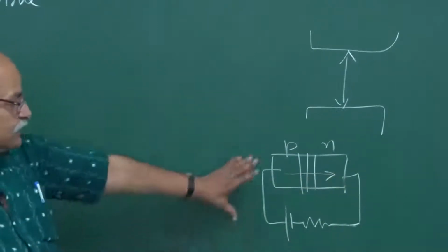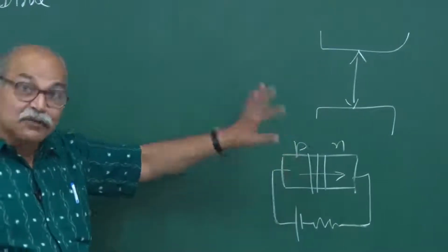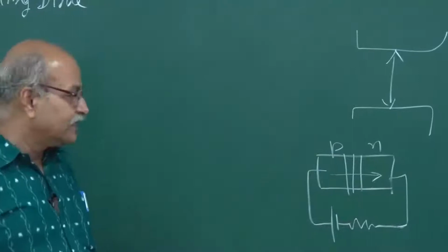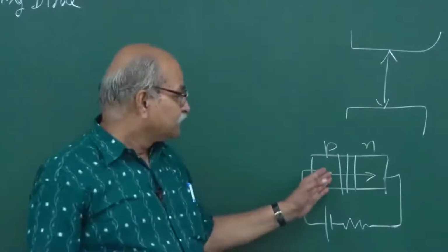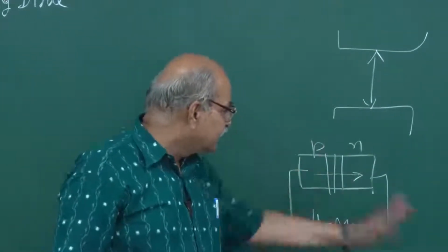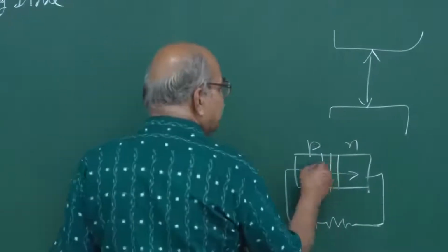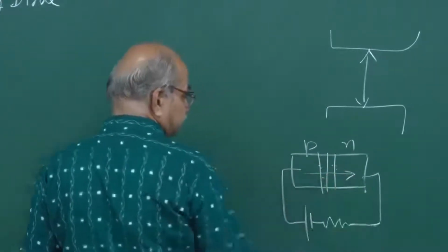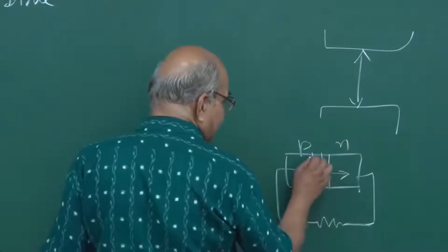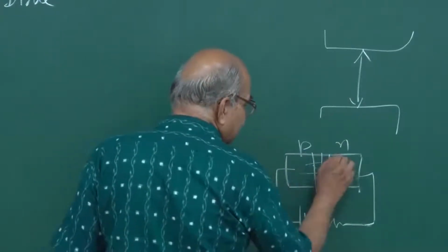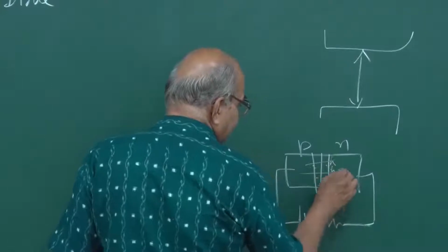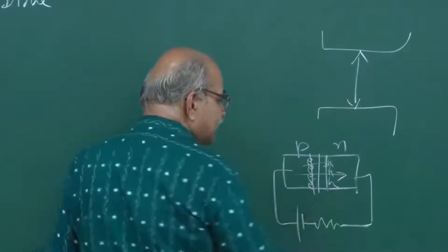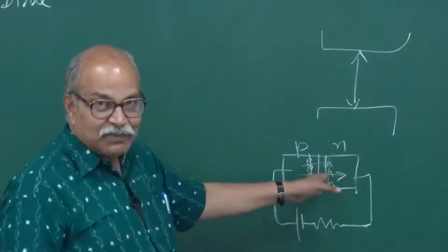You have reduced the barrier, so the diffusion current has increased manifold, the usual PN junction theory, and because of this increased diffusion, these majority carriers diffuse through that depletion layer. If you have lots many holes here, they diffuse on this side, and the electrons, they diffuse on this side. So, you have minority carrier injection, if you remember, right.